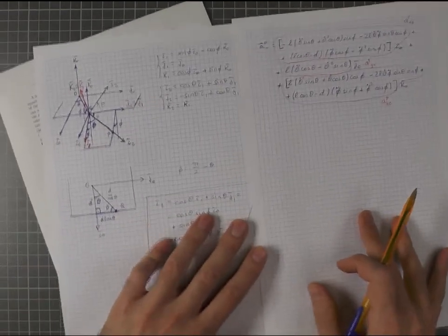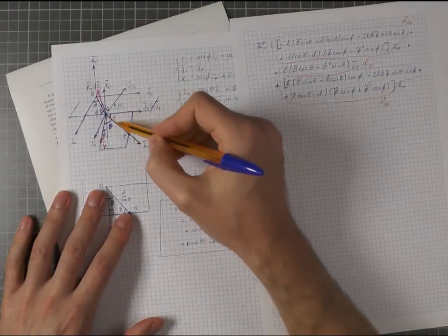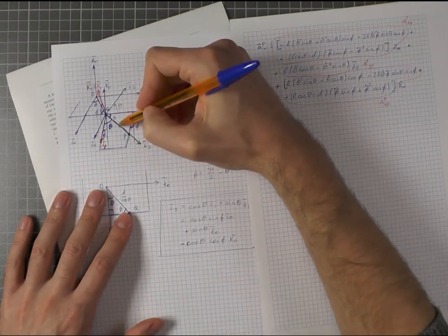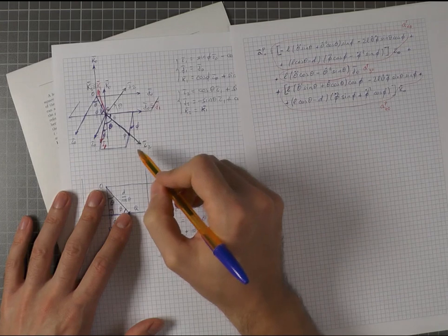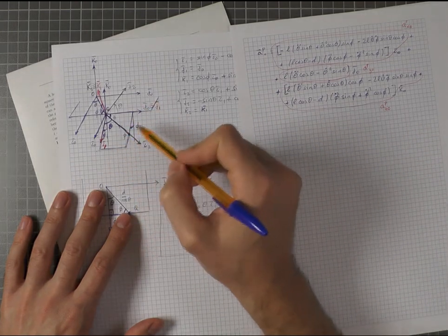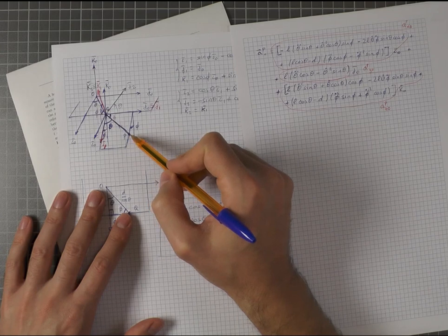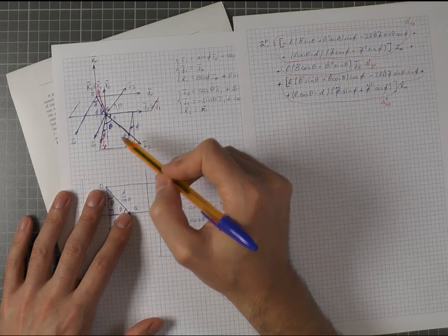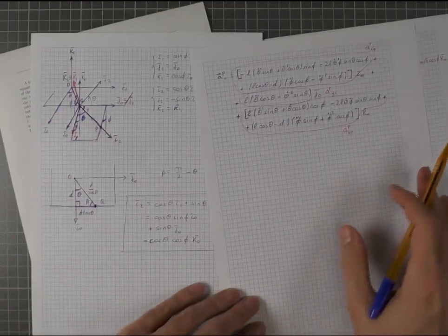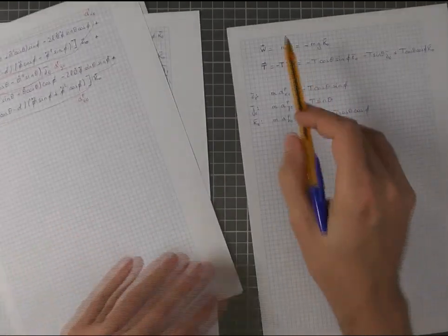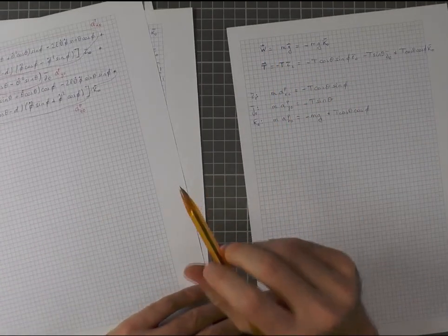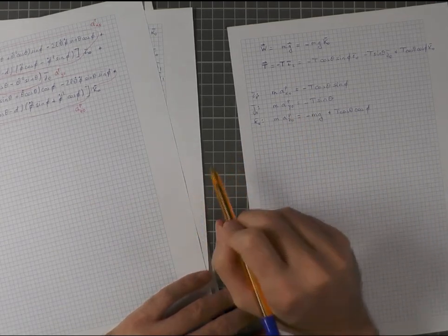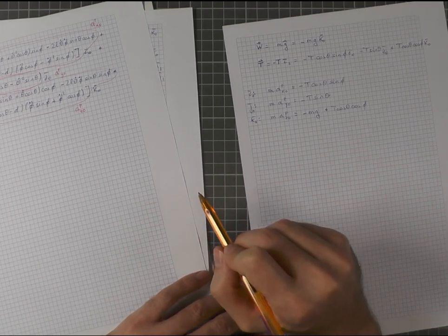And that would have been possible, okay? As you can see, we already have a basis where one vector, I2, is in the direction, actually in the negative direction of the tension, okay? And two other vectors, J2 and K2, are perpendicular to this segment, okay? So if we had expressed our acceleration in that basis, and if we have projected our forces in that basis, we would have already obtained one equation that depends on the tension, all right, but two other equations that are free of the tension, okay, which is the expressions that we are looking for.